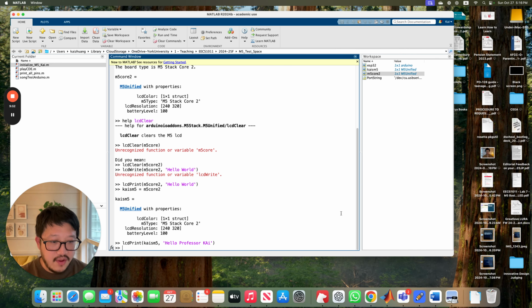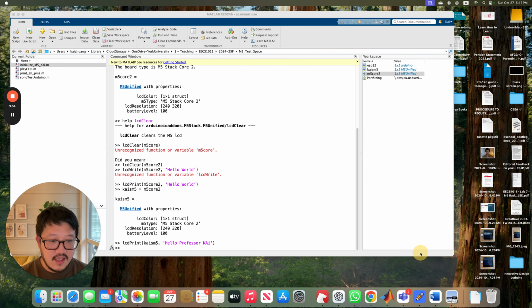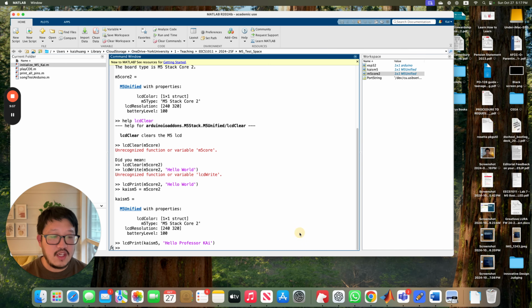All right, so now the last thing we're going to show is we're going to connect to the NeoPixel. The way to do this, you can use the same code. You are going to do add ESP32. That's the connection to the particular chip, the Arduino chip. We're going to use the library Adafruit NeoPixel. That's the library we installed to control the NeoPixel strip. This is going through pin D25. Just use this. That's how we made the connection here, right?